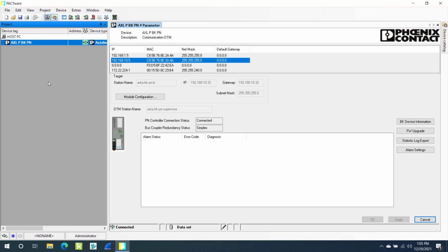Earlier, we were showing Acyclic F with Startup Plus. Acyclic P is not on Startup Plus. You can do all the configuration in Startup Plus that you've seen through our DTM here, through the device DTM. But what Acyclic P has, which is nice, is you can actually do the HART communication DTM. It is also possible to do everything that we're showing you using the Acyclic F AI8, but you need a PLC Next 2152 or 3152.